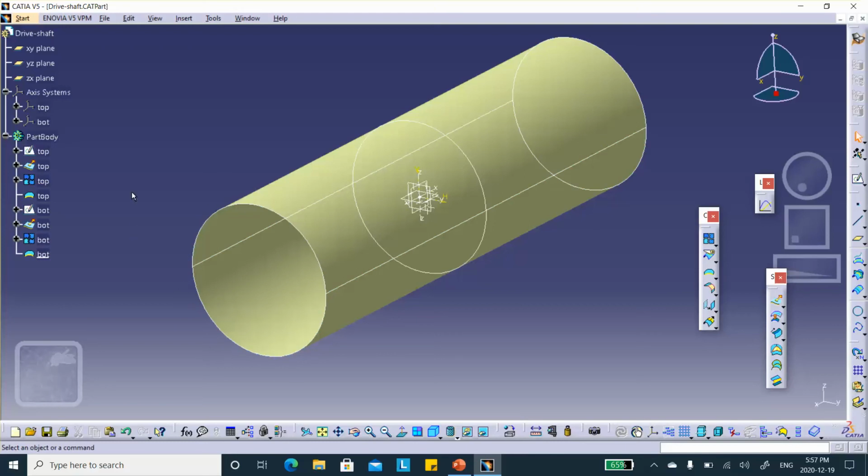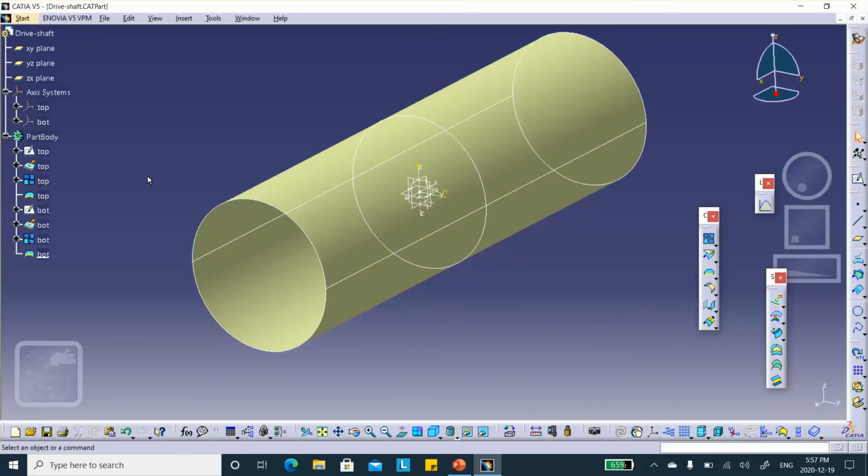But I suggest that we use a virtual part so that the point of application of that moment or torque is not directly on these edges, but at a different point, and it's going to transfer it. If you do not understand this, it's okay. Just go on later, clamp the ends and apply the moment on these edges. But you learn something new here.